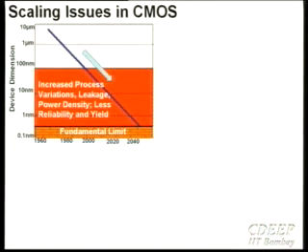So, going through the silicon scaling issues in CMOS, this is something that we have gone over last lecture too, but I thought for the sake of completeness, it's a good idea to talk about some of the scaling issues again. As device dimensions are being scaled, once you go below, for example, 65 nanometers, there's increased process variation, and we talked about it last time, increased leakage current.